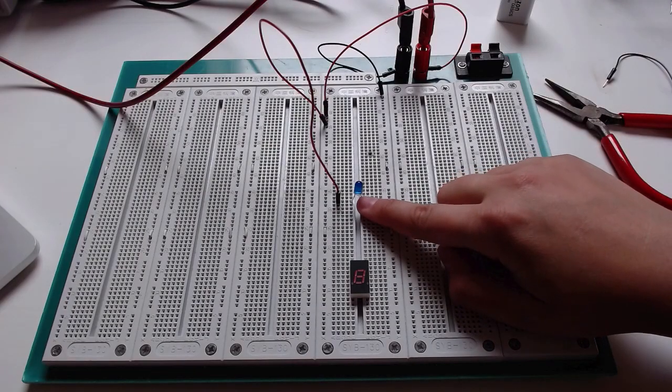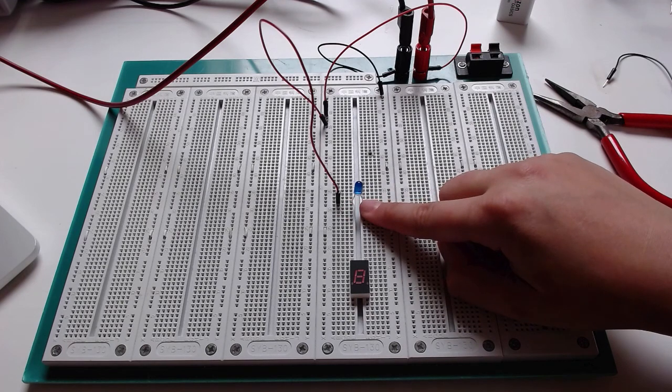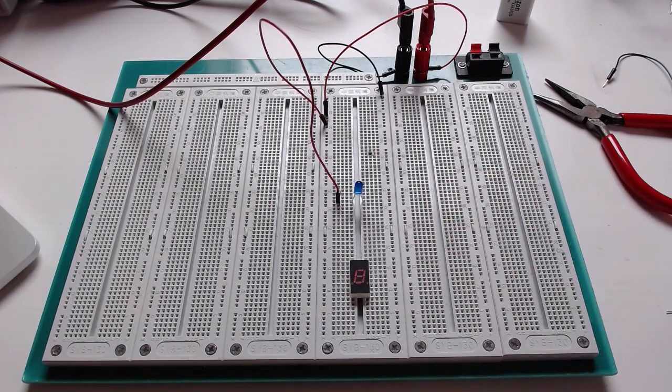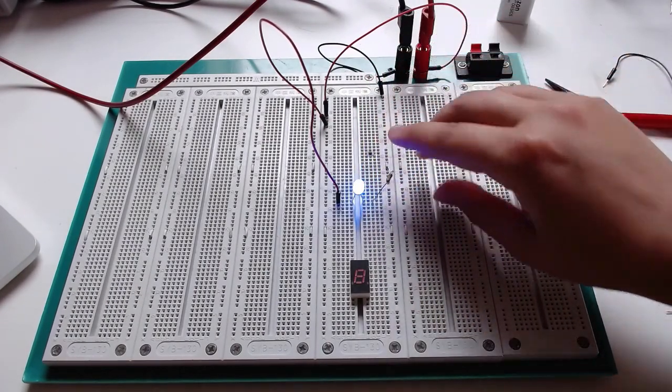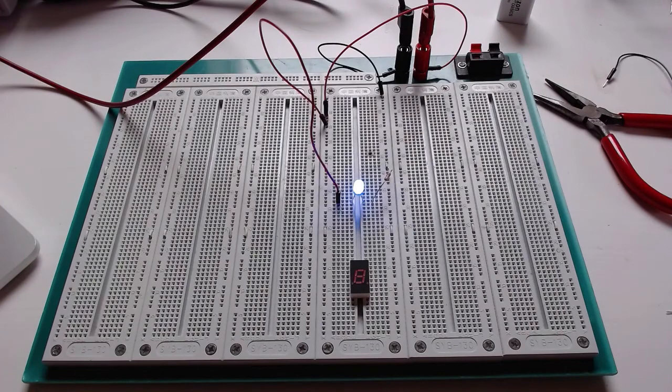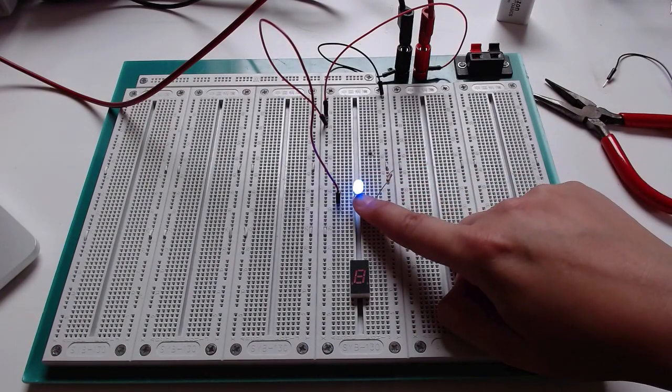So because we're going to use a supply of 5 volts, and this guy drops 3, if we subtract those two, we get 2 volts. Divided by 20 milliamps gives us 100 ohms as the smallest resistor that I'd want to put in series here. Okay, so I'm going to throw a 220 in just because that's what I happen to have on hand. So that's great. As long as it's over 100 ohms, I can be assured that this guy is not going to melt.